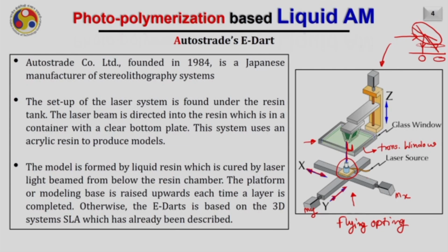On the other hand, as you are projecting the light from the bottom, the amount of liquid required will also be very little. We discussed the same thing when we were discussing the DLP based technology. In this case, the minimum material required will be equal to the layer thickness of the object. Unlike in the case of top feeding systems where there is a big tank of liquid and you have to dip all the time, and the entire tank should be filled with the liquid photopolymer. Here in this case, the inventory is quite less, hence the process is quite economic.